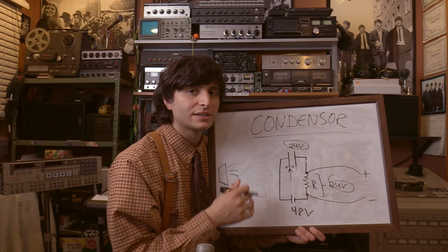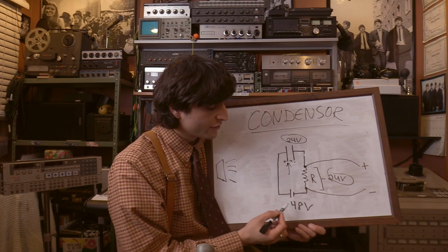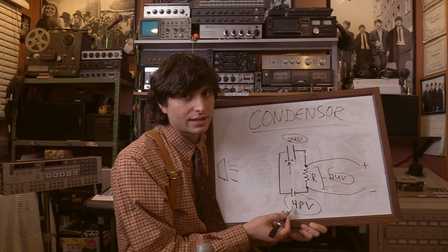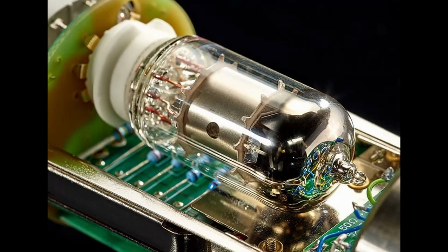And that's most often seen in vintage style condenser microphones where vacuum tubes need higher voltages than is provided by the standard phantom power of 48 volts. Because condenser microphones have active electronic components, they are going to be much more sensitive to the sound pressure. And as such, you need to be careful when using these microphones up to a loud source.